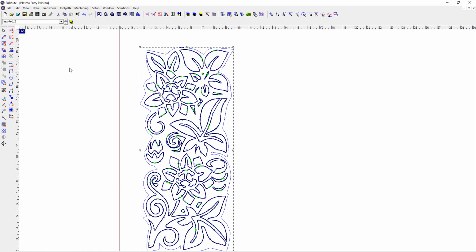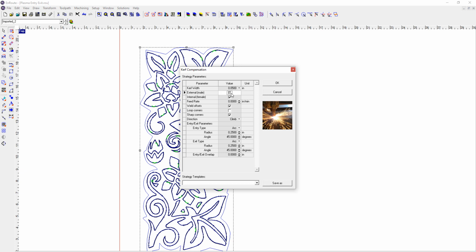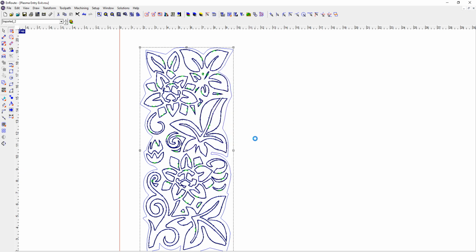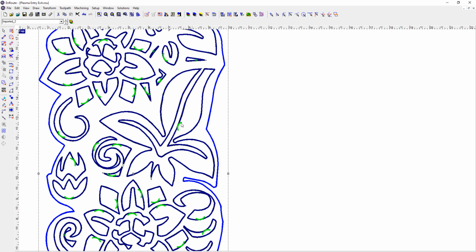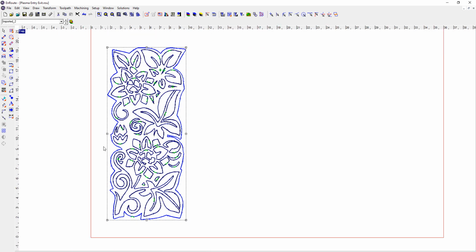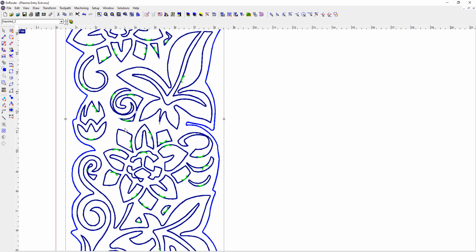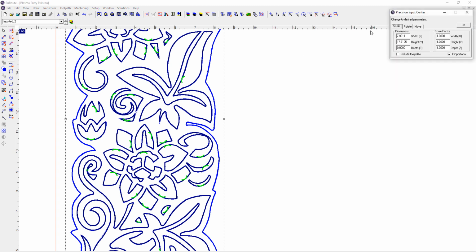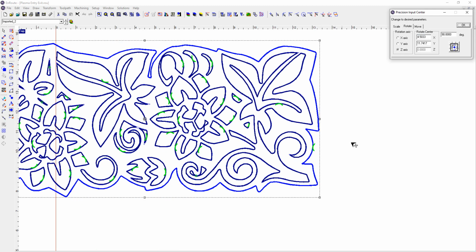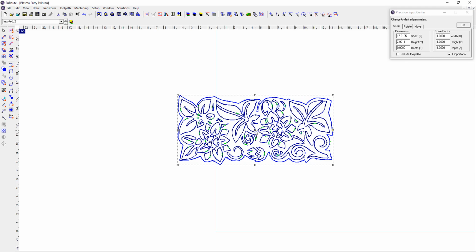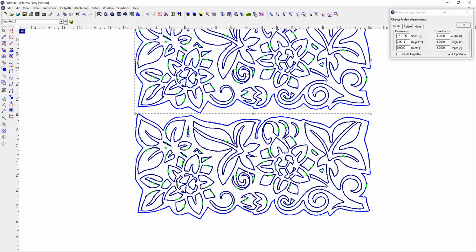And now we can put our toolpath on the outside of this as well, external, and that can be placed wherever desired around the outside there. And next thing we'd want to do is just group these together by selecting them and hitting Control G. That way if we move everything around, it's going to maintain those positions. Now I can come here and I can rotate this, say 90 degrees, and hit OK. And that's not going to change those start point locations. I can even make a copy of it. That does not change the start